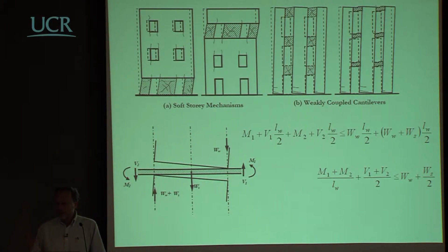It can rotate. So in a way, what I'm trying to say is that if you take a situation here, for example, and you have some floor here, then you have the weight coming from the floor, the weight coming from the upper part of the wall, you can have something like this because the floor is trying to rotate, and is trying to rotate putting some reaction into the wall, and also its own weight is trying to react.